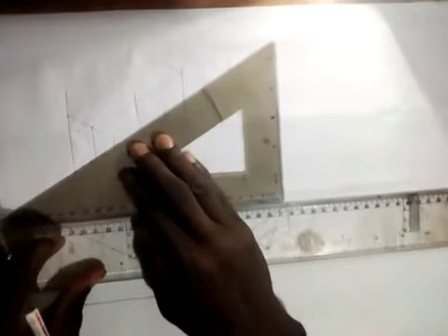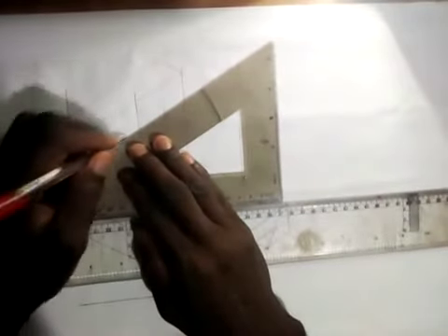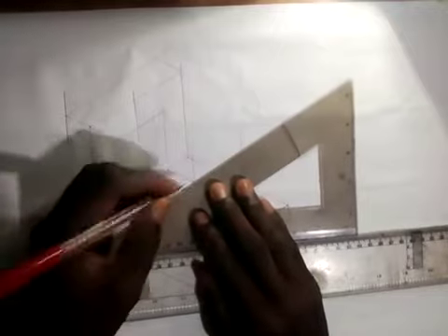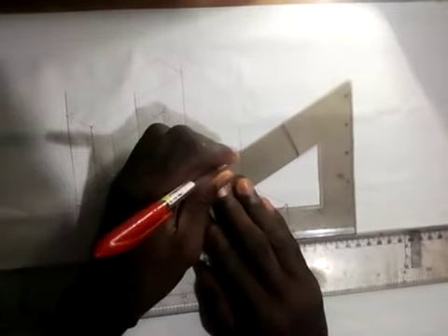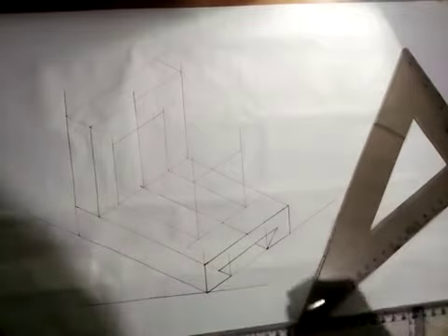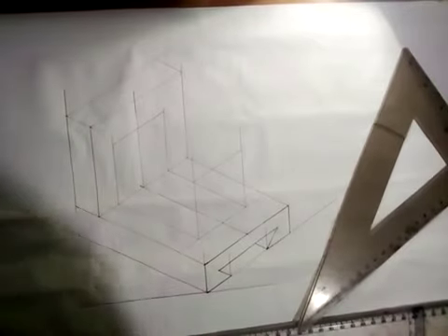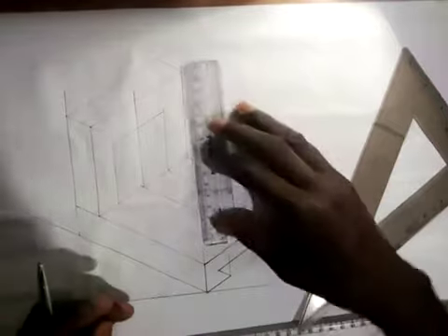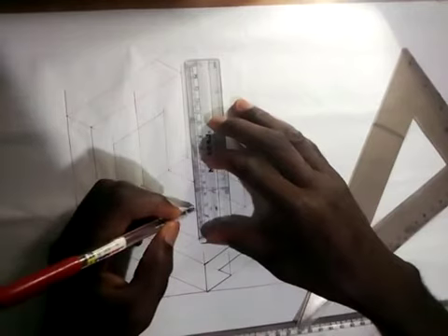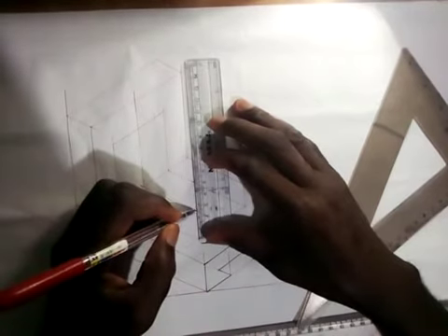So here I'll transfer this to this side. And here also I will transfer this point onto this line like this. So I formed a square here and I formed a square here. So I believe you can see what I'm doing. The next thing I'm going to do is that I will need to divide. If you have watched my videos on construction of isometric circle, this should not be strange to you, but I'm doing it if you have not seen it before.